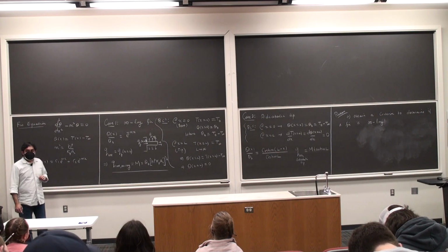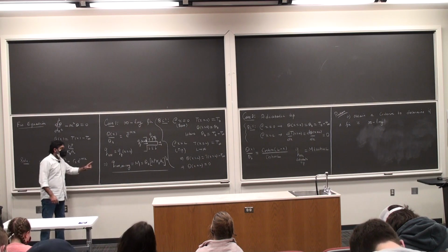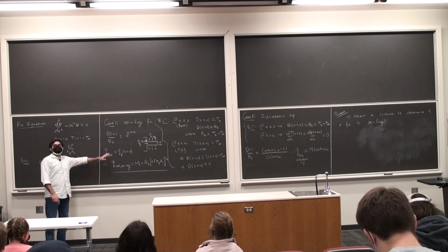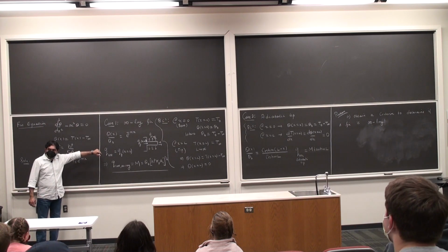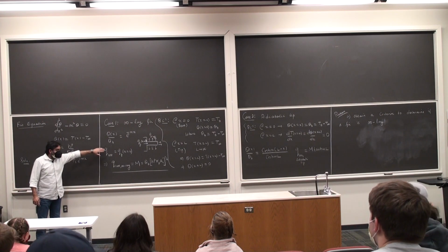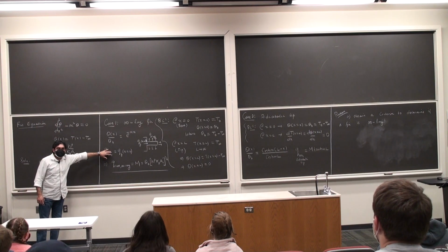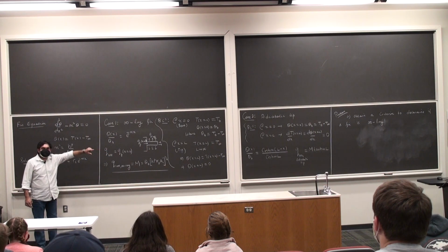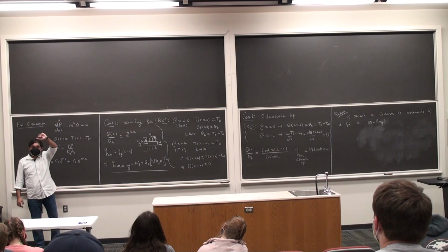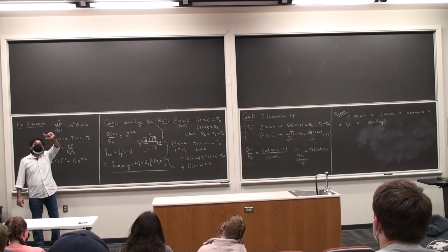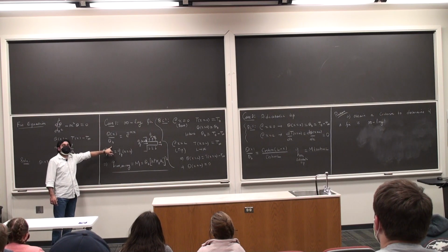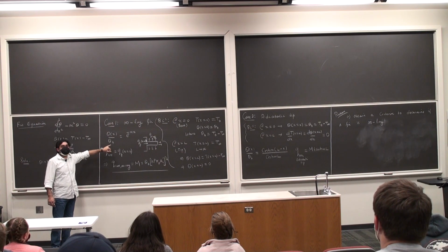Alright. So look at the infinitely long fin, okay, this panel here, all of it. If I look at the boundary condition at the tip of this fin, what's that going to be? Remember, the infinitely long fin is such that its tip is at the temperature T infinity, yes sir? Oh, so there would be not the zero, it would be zero. It will be zero, so this is actually a limiting case of the adiabatic fin. You see that? Does everybody see that? The temperature at the tip of the fin is T infinity.